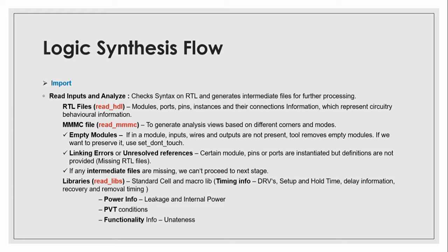We have to analyze it from the log file, and if we see such empty modules, we have to discuss with the design team whether we need to preserve them or not. If we have to preserve them for future reference, then we have to set them as set_dont_touch in the constraint file. Otherwise the tool will automatically optimize them, that means the tool will automatically remove these empty modules if it can't find proper definitions.